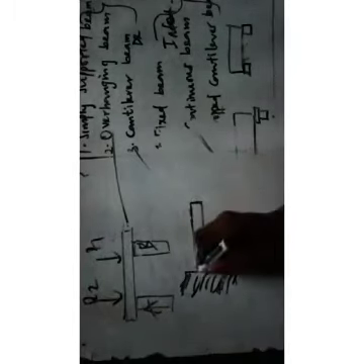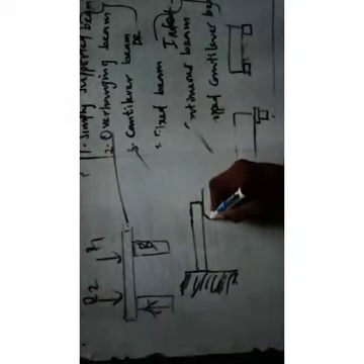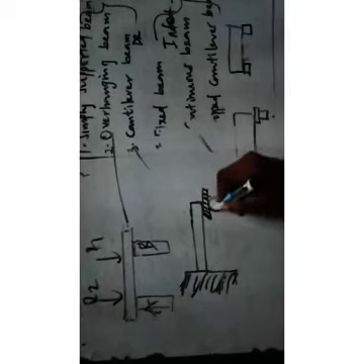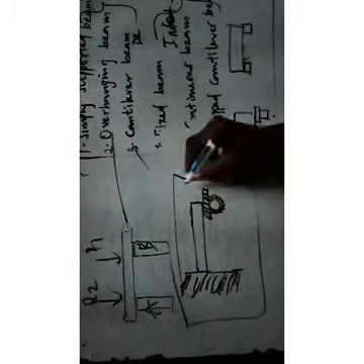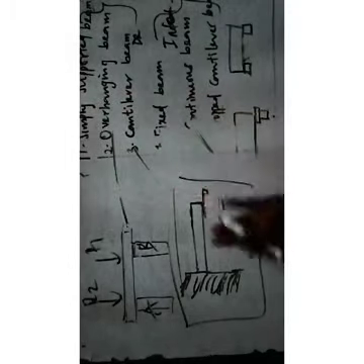So in this case, if I put this on a roller, this is an example of a roller. A diagram of a roller is like this. It's like a ball. This roller can move. Now this has become simply supported. If one side is a hinge and the other is a roller, it's simply supported. But if there is no roller there, it's just like this. This is a cantilever.